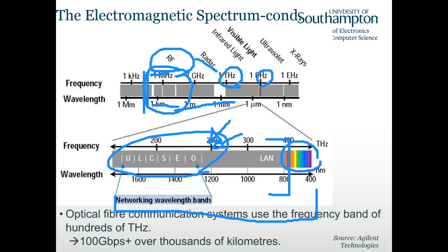So I'm not sure if you remember that in the first part of teaching, we discussed why we didn't use millimeter wave before 5G and why we start to use millimeter wave. So first of all, rule of thumb, as frequency increases, we would have more available bandwidth. So we want to use higher frequency band. However, another rule of thumb, as frequency increases, the antenna aperture, so the antenna size, would become smaller. So in the past, it's very hard to manufacture. But in the era of 5G, we can manufacture this antenna for millimeter wave.